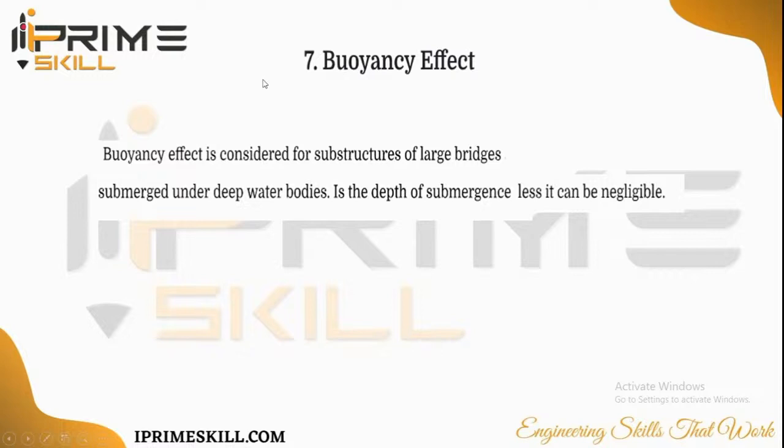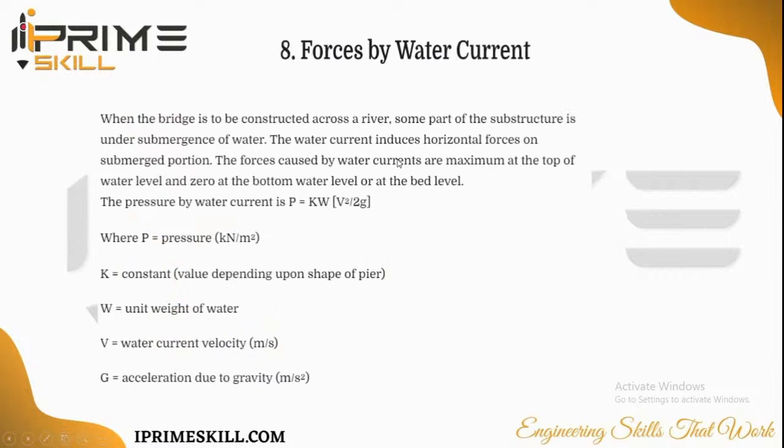Buoyancy effect: when you want to build submerged substructures in water, you have to consider deep water bodies and all these things. Sometimes it's negligible, but you have to consider it. Then water current: if you are going to build the bridge on water, then water current forces should be considered. Forces by water currents are maximum at the top and zero at the bed level, with a trapezoidal distribution. That is the formula that you have to use.